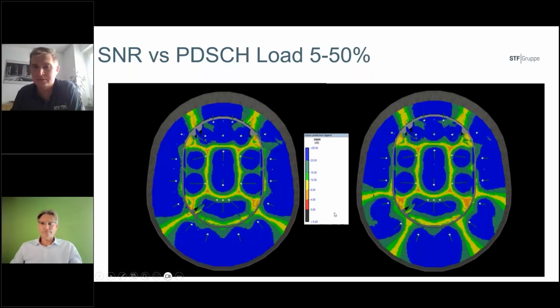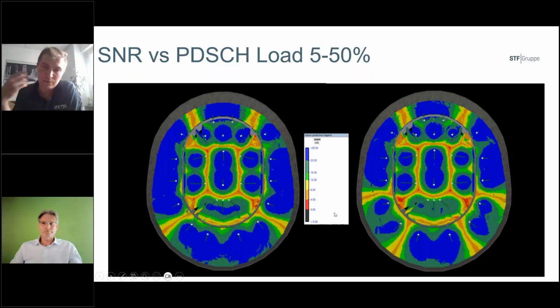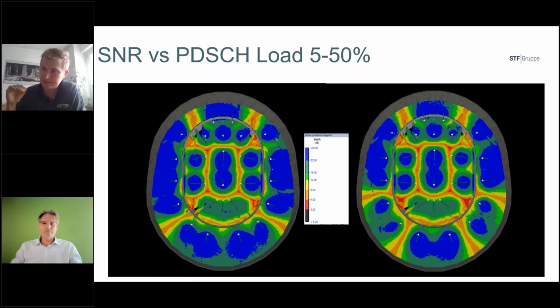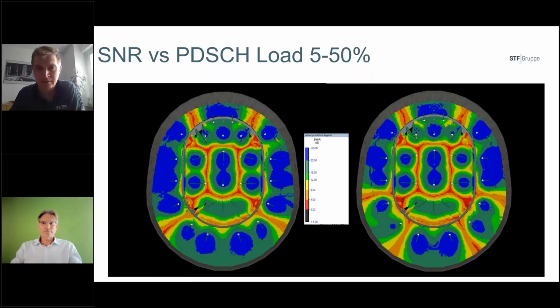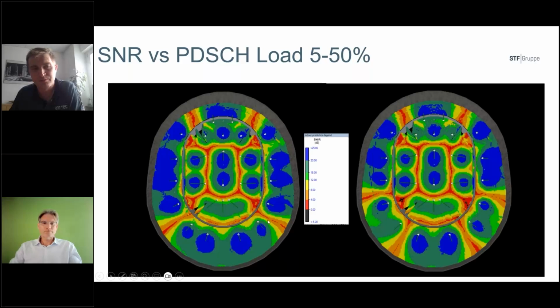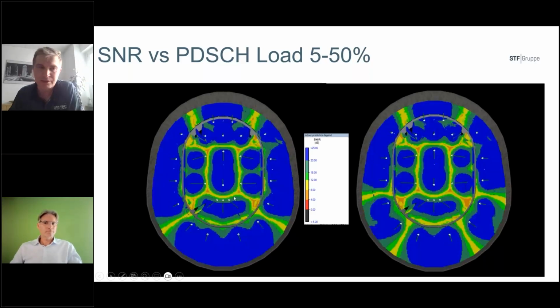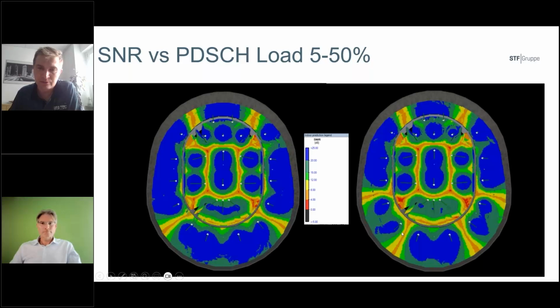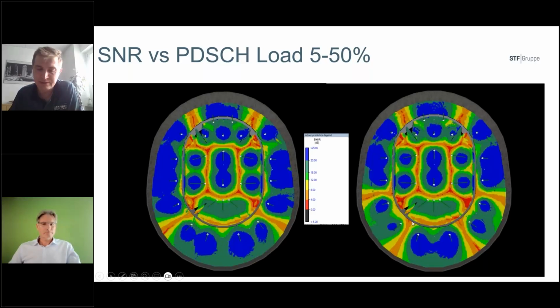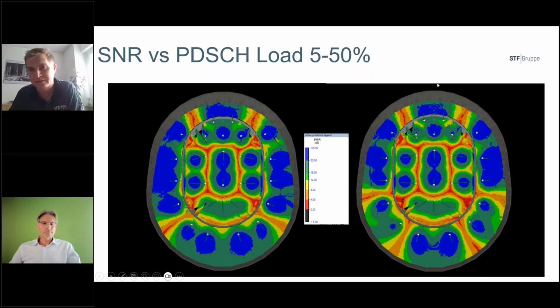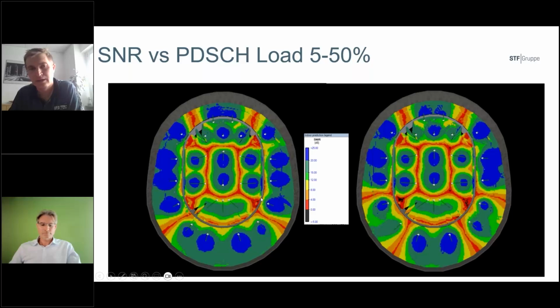SNR is here in the middle, so you may observe on the visualization what would happen if the load factor is increasing, and whether 8 cells would be enough. Actually, from this selection I would prefer the left design, because the total area of degraded SNR is a little bit more with 10 cells.